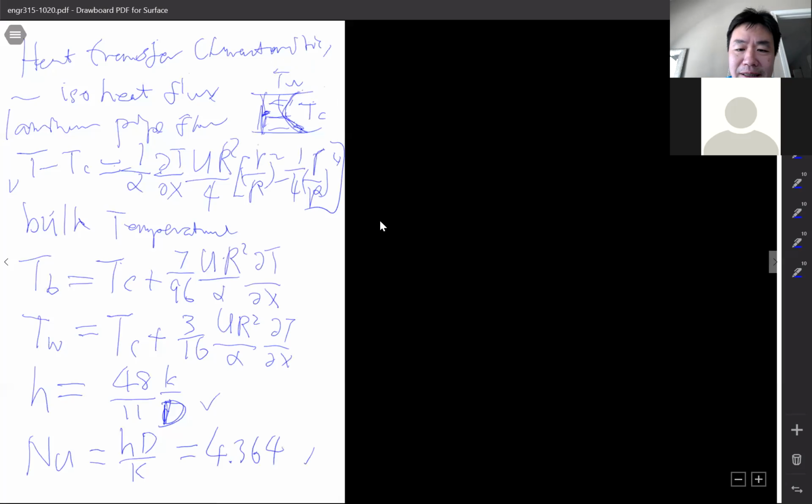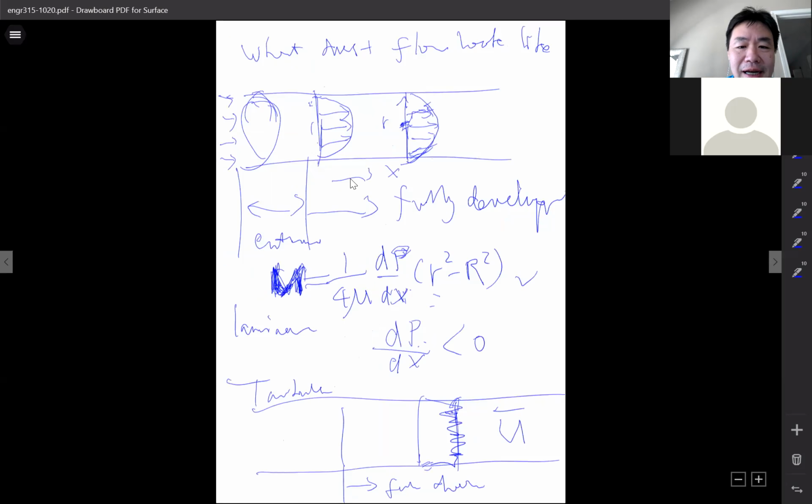So last time we did the flow side. For laminar, we even have the analytical solution for the velocity profile. For turbulent it's even easier. It's just like a uniform velocity for turbulent pipe flow. Although the velocity is chaotic and fluctuates all the time, it fluctuates about a mean value, so it's okay for our practical engineering purposes to take the average value.